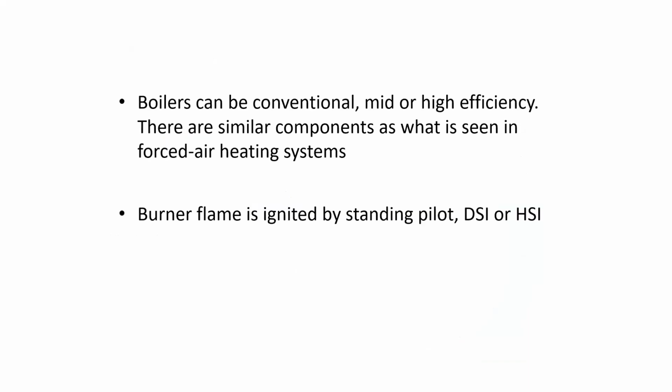Flame ignition and flame proving. Boilers can be conventional, mid, or high efficiency, and they have very similar components as what is seen in a forced air heating system. The burner flame is again ignited by either standing pilot, DSI, or HSI, depending on its efficiency value.